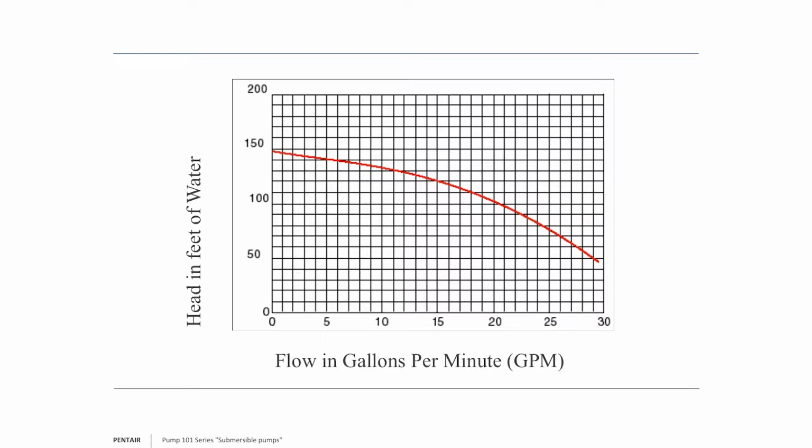So now I also want you to understand the pump right now we're talking about is a single speed across the line contactor, meaning being run by a pressure switch, for example. So the point's closed and that pump's going to run at one set speed. Knowing that, I want you to understand the pump can only do what the curve will allow it to do.